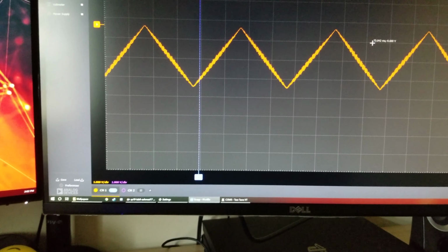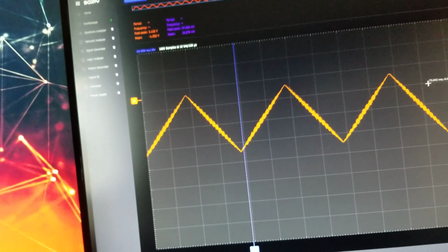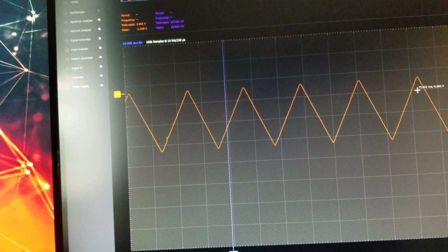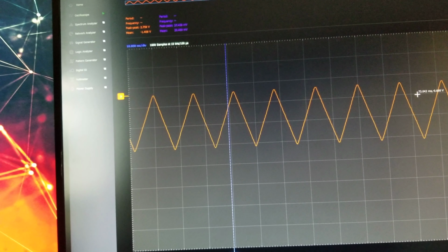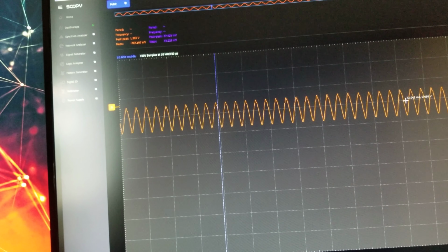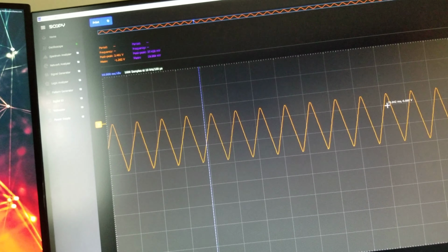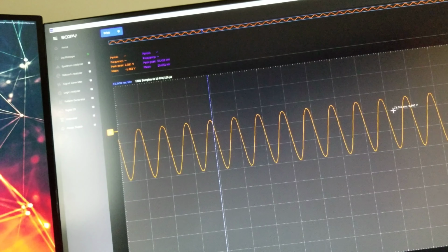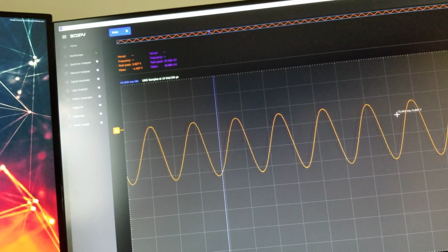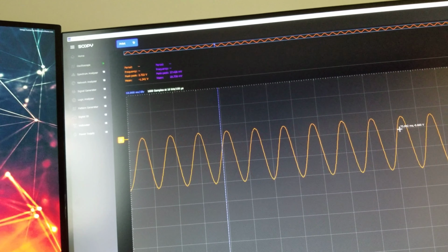That's because of the time constant again. You can start seeing the capacitor charging and discharging. It looks much better if we keep it in a higher frequency range. But again, as we increase the frequency, the filter makes it so that the amplitude doesn't look as nice. And then changing over to the sine wave, we can see it does the same thing. I'm decreasing the frequency and increasing it.